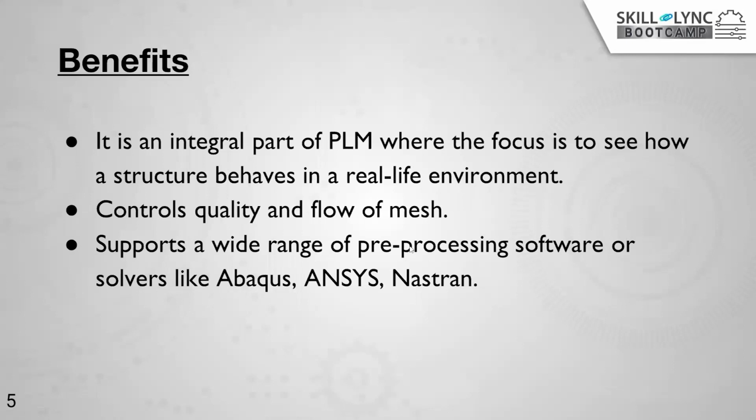What that means is that before starting the meshing operation, you can set which platform you are meshing for. If you select Abaqus, you can mesh considering all the functionalities in Abaqus, and prepare a deck file which you can directly submit for a run in Abaqus, and get the results. Similarly for Ansys, Nastran, Marc. That is the reason companies prefer Hypermesh as a pre-processing software: companies whose geometry is way too complex and who want high quality mesh, because quality is directly proportional to the correctness of results.